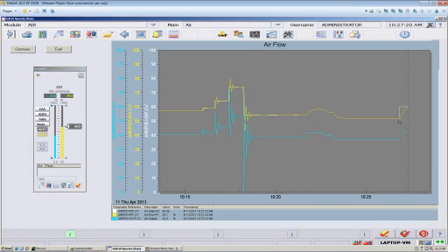So I started at 10:26 and 49. 48 seconds later is 10:27, 37. So right there, right now, is when I predicted we'd be 98% of the way to new set point, and predictably we are. So we've tuned our perfect idealized air model in just a couple minutes and got the results that we chose, we selected.